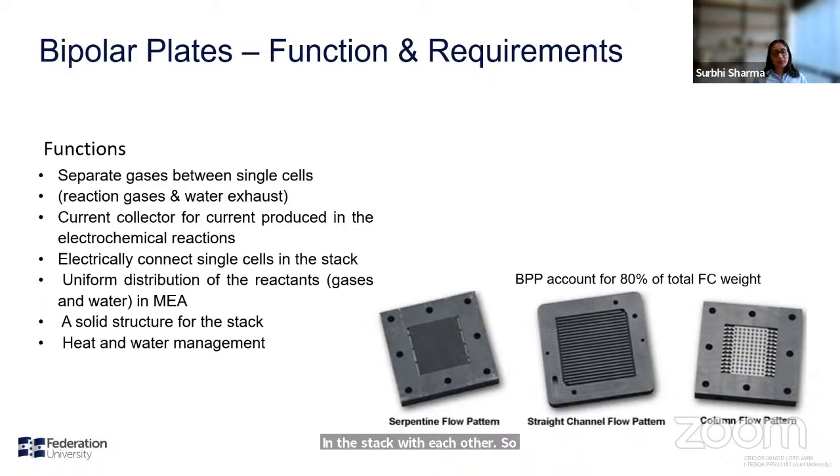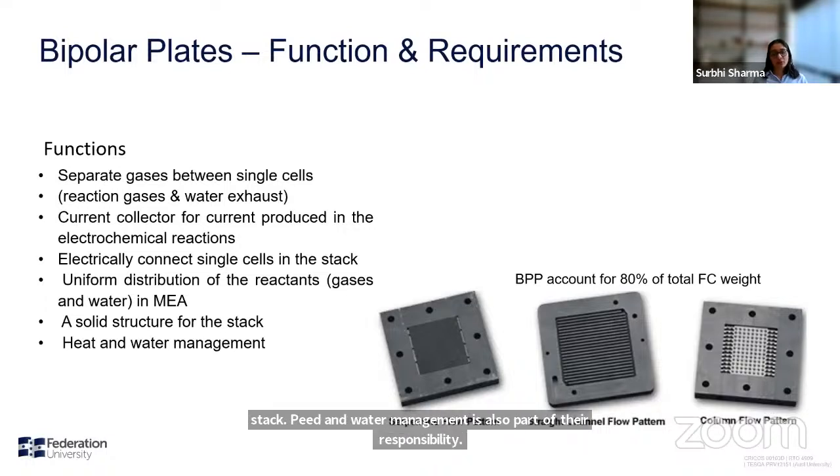So its purpose is to ensure that there is uniform distribution of the reactant gases that are supplied into the anode as well as the cathode. And it also provides a solid structure to the whole stack. Heat and water management is also part of the responsibilities. So it's another important component of the fuel cell system.